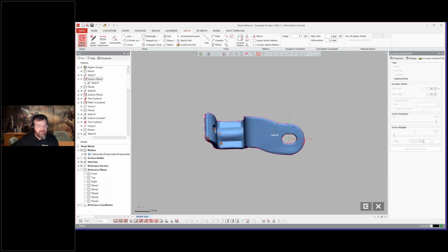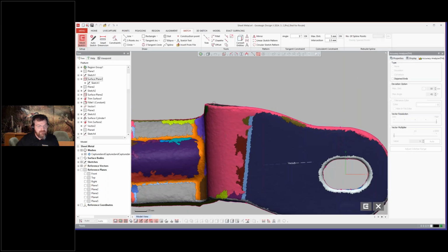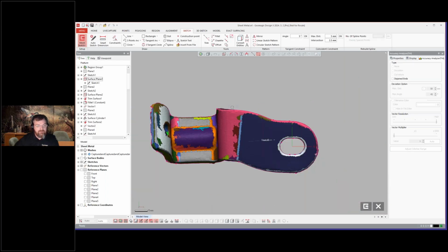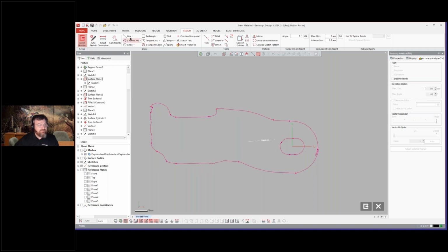Come in and create a sketch. And then you'll notice that this will help you determine that the entire part is not in the same axis. But what I wanted to bring out is you can use the silhouette just for this area and sketch all the way around here and create, just like they did, the surface trim for this area alone by sketching all of this, using all these tools here, like so. So you can see that all of the sketching tools will fit directly to the silhouette geometry there.